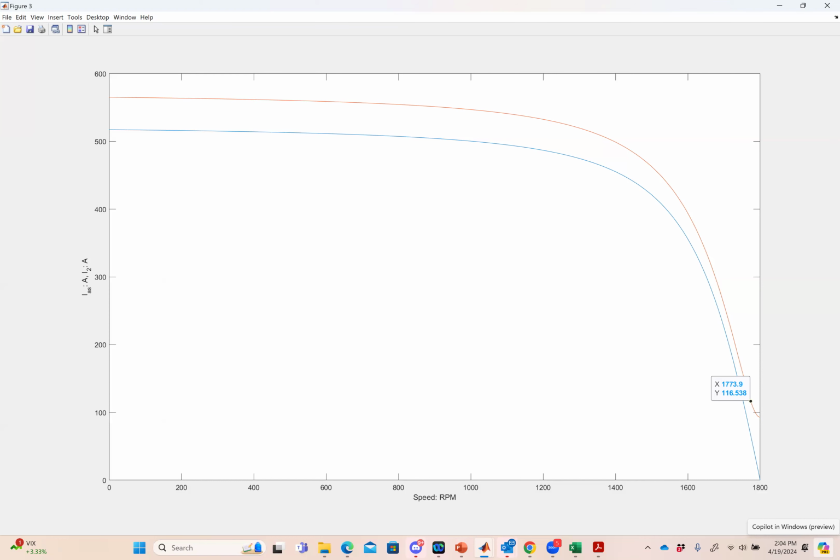What's going to happen to the temperature of that motor? It's going to increase significantly, right? The current here, this is what's important. That current, let's call it a factor of 5 higher than it is at rated, okay? A factor of 5 means how much more heating is happening in there? 25 times more heating, right? Because effectively it's 5 squared. Remember, it's I squared R. So there's 25 times more heating. That guy's getting hot fast. And that will definitely have a pretty negative impact on the windings in that machine.